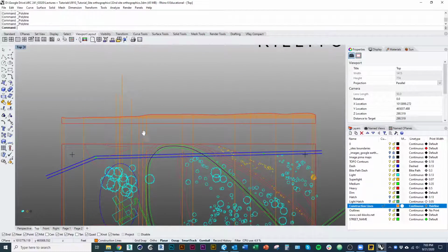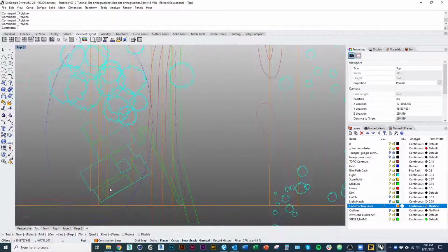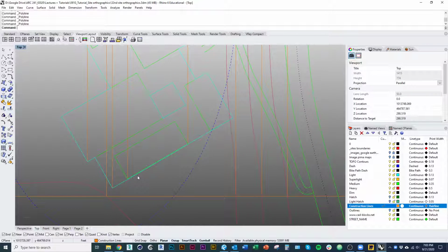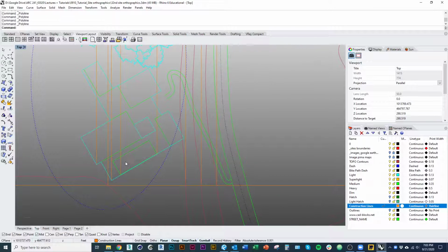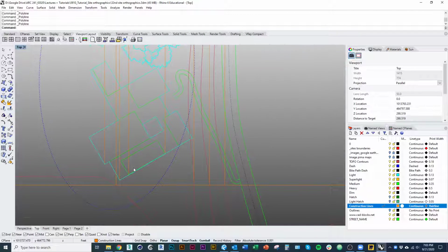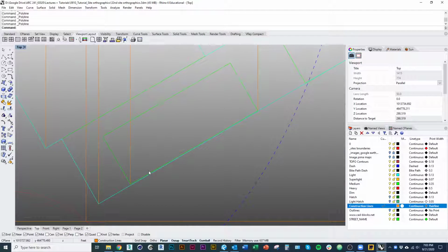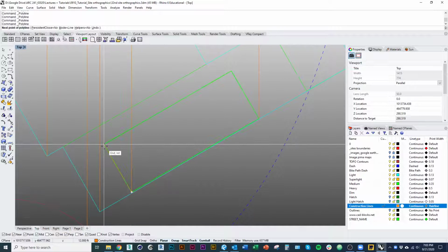Draw a bunch of lines up. Let's start with these 3 points, right? So this is kind of a deck area. This is what's going to become a wall and a roof, like a tilted up roof. Now, I'm going to, well, actually I can do this a couple different ways. What I'm going to do to make it easy on myself is this line here is 12 feet. I'm going to use a 30-degree roof pitch.